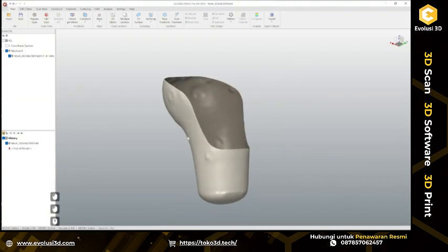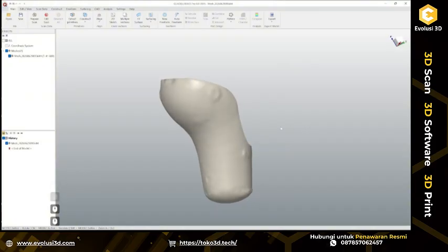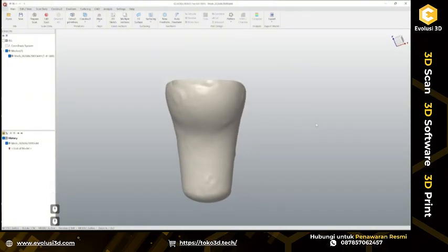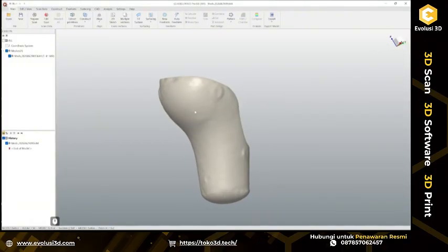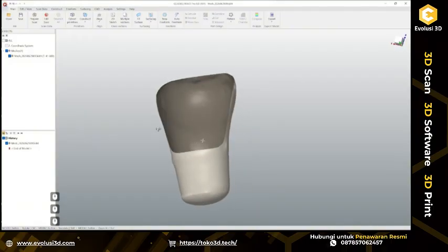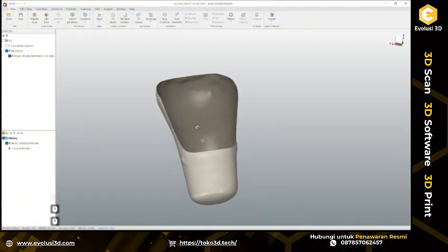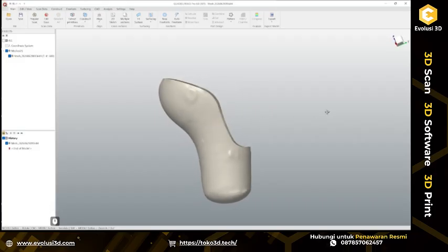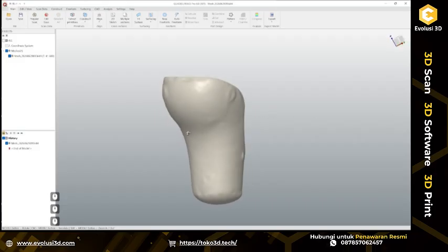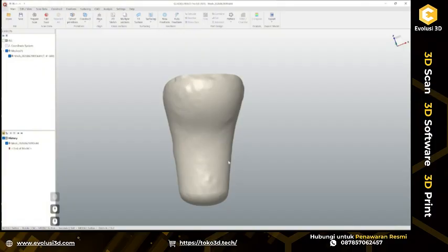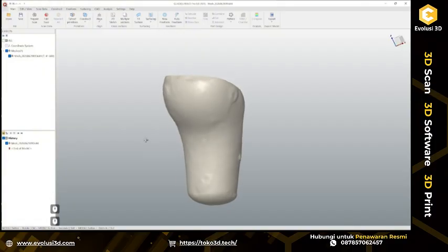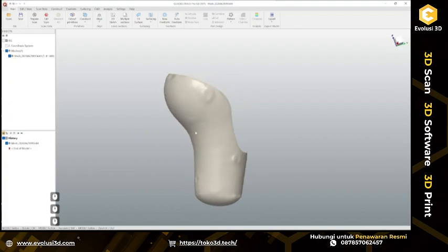And just before diving into fitting primitives exactly, I want to make sure my scan data is aligned to the coordinate system, because I will want to create cross sections and I will want to probably split this part in half to mirror it to the opposite side, because I think it's not super perfectly symmetrical. So let's go on and do this.